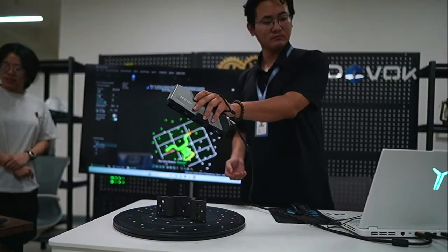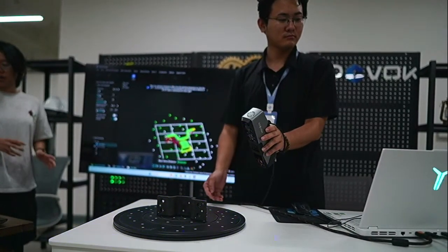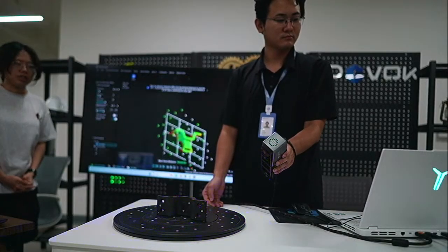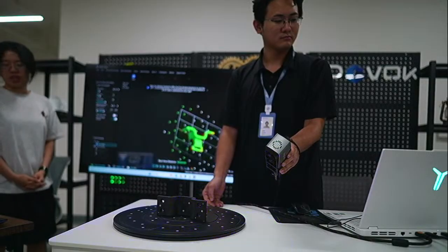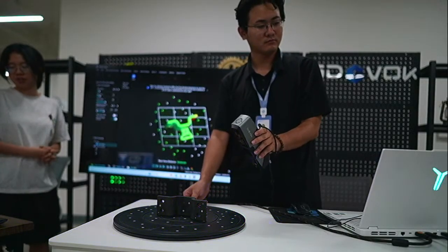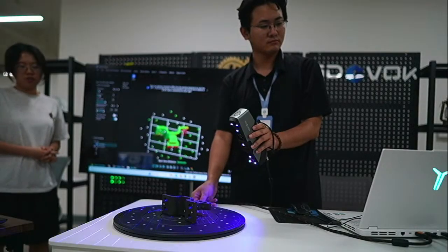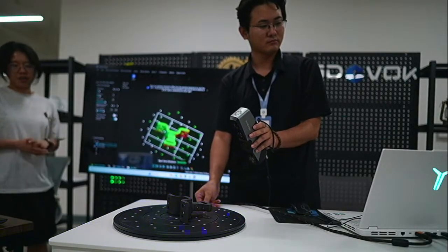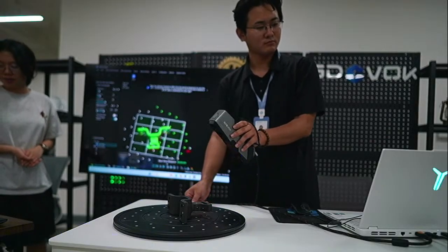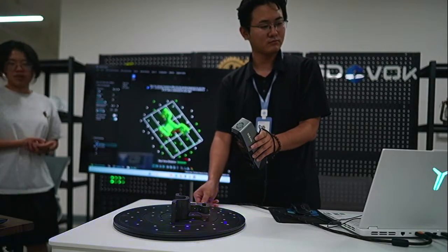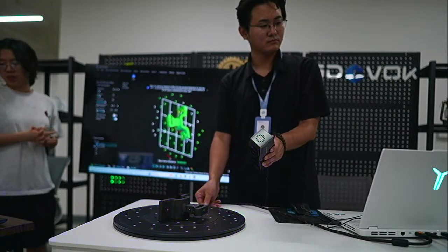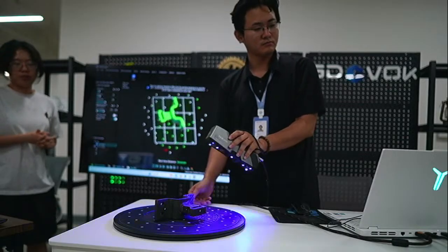So we have scanned the markers, so we started scanning the industrial part directly. We are using the 0.5 resolution to scan this industrial part, and I will scan the front side first. Slowly rotate the turntable so that every angle of this industrial part can be scanned. With the blue laser marker mode, we can achieve the highest accuracy of up to 0.04 millimeter.